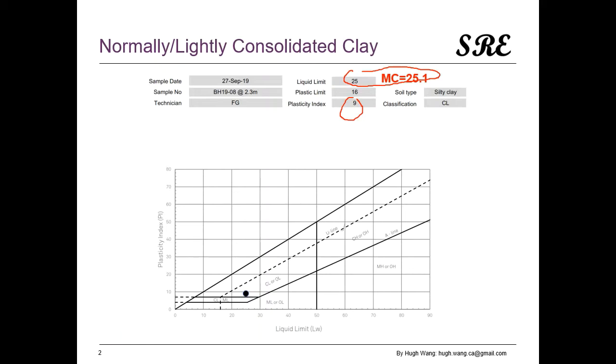I think there's some error in the moisture content test, but however, at least give us a ballpark estimate of the behavior of this material. So after we look at this, the important thing will be what problems could happen for structures built on this clay. In the following, I provide 7 aspects to consider in the design. Depending on the nature of the project, engineering measures are required to address some or all of them.